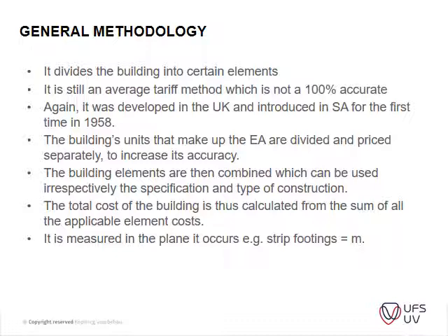divides a building into certain elements. It is still an average tariff method, which is not 100% accurate. Again, it was developed in the UK and brought to South Africa in 1958. The building units that make up the elemental analysis are divided and priced separately to increase their accuracy. So the main thing is you're just dividing the building into certain sections, but it is linked to the